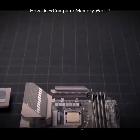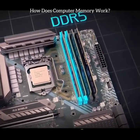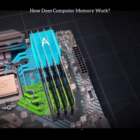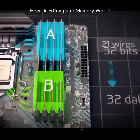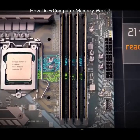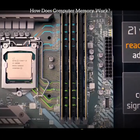Let's move back to see the memory channels. For DDR5, each memory channel is divided into 2 parts, Channel A and Channel B. These 2 memory channels, A and B, independently transfer 32 bits at a time using 32 data wires. Using 21 additional wires, each memory channel carries an address specifying where to read or write data, and, using 7 control signal wires, commands are relayed.